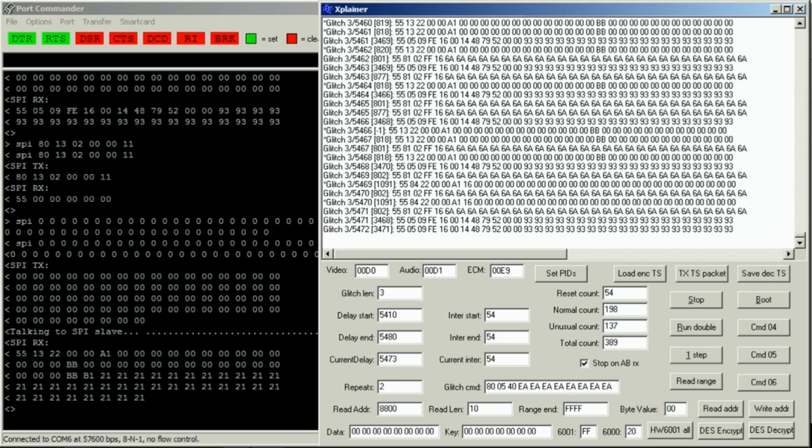There's a 2 kilobyte area of ROM that, if I attempted to read, causes the chip to reset. This area of ROM contains the personalization routines, and those are never supposed to be used after the device leaves the factory. There's also protection against modifying the seed keys in RAM. Trying to store a value to these locations appeared to do nothing.